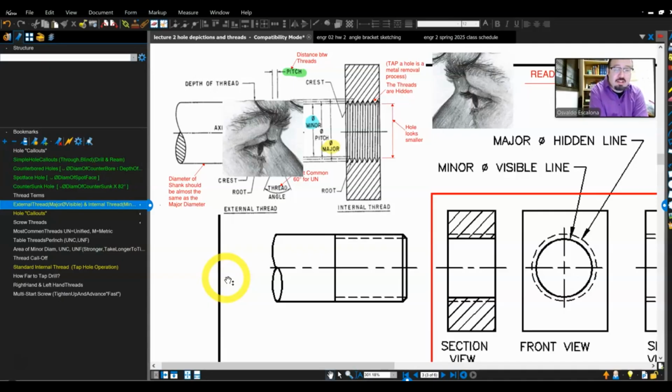You can use a drill bit. You can use a reamer. You need a reamer for special diameter applications. You might need a counterbore for the bolt to sit on, and you need a counterbore that has a square seat down. For the counterbore, you need to give the depth.